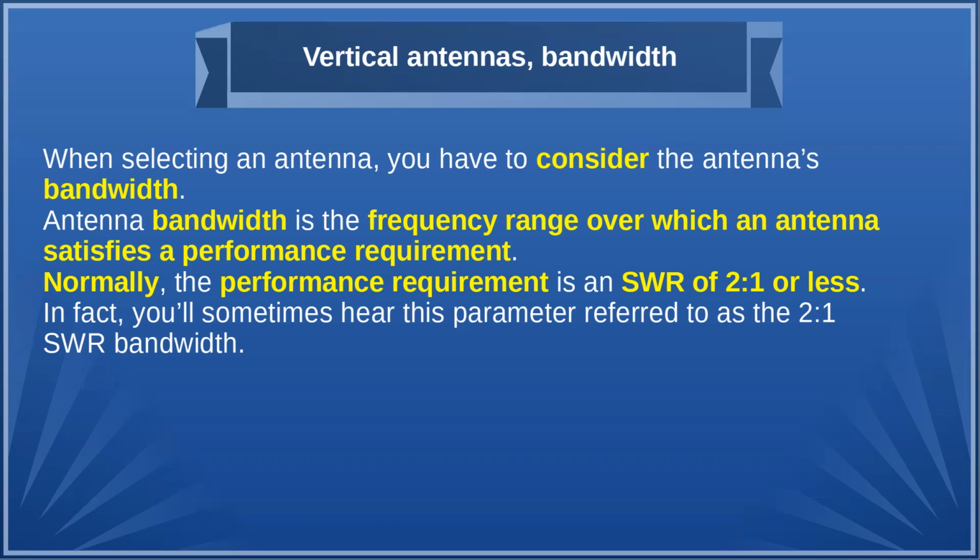My performance requirement is 3 to 1. Your tuner will easily tune 3 to 1. Not that you're not losing some performance, depending on how far away your tuner is from the antenna. You're just tricking your transmitter into outputting, but your antenna performance may not be that good.